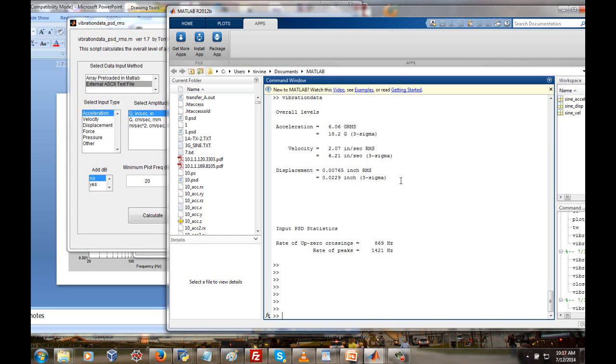And if any of those limits are exceeded, then the circuit breakers trip and the test gets shut off. And that's not a good thing. That causes some problems and consternation. So before we ever do a test on a shaker table, we want to review these types of parameters here to make sure that they fall within that shaker system's capabilities.